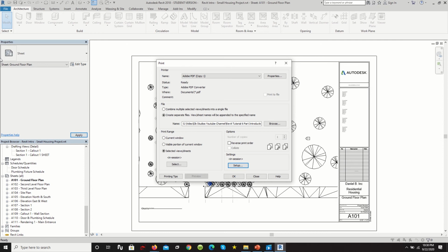But then you're going to notice that nothing saves. So what you're going to do is do the same thing, go on file, print preview, then hit print, and then you will be able to click and select these things. If that's happening on your computer, I can't really explain why that's the case, but Revit tends to have this glitch and has many bugs that really need to be fixed by Autodesk.